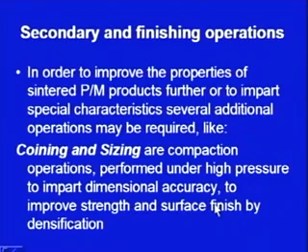So now we have seen that in the basic powder metallurgy process we make the powders, then we blend the powders together for certain properties of the final product, then these are compacted. After compaction, sintering takes place in which particle to particle bonding takes place, density improves, and porosity is also affected by the sintering process. Later on, we enter into another phase of the manufacturing process of powder metallurgy, that is the secondary and finishing operations.